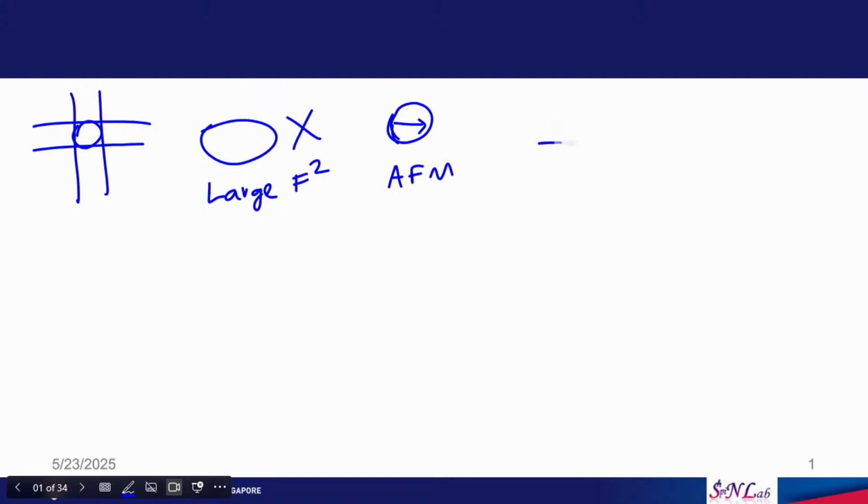the ferromagnetic layer. If you have an MTJ where this is the reference layer, then this is the magnesium oxide layer, then this is the free layer. In order to pin the magnetization of the reference layer in one particular direction, we use an antiferromagnetic material.